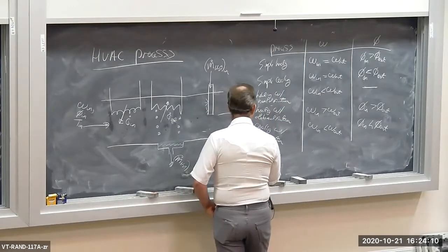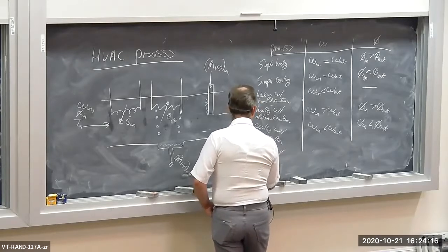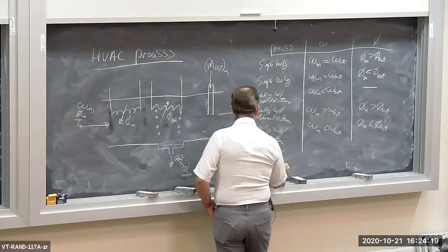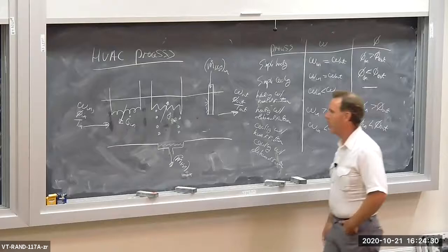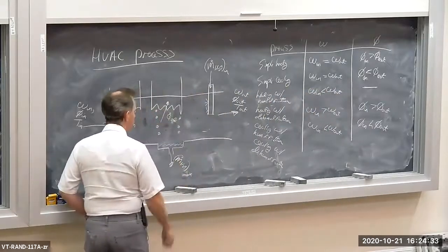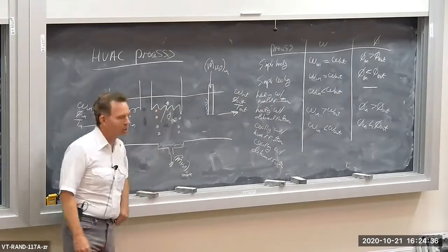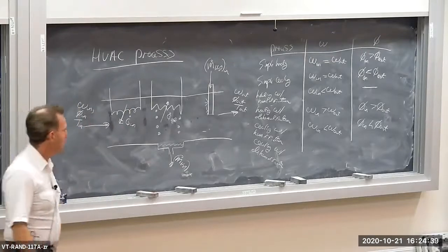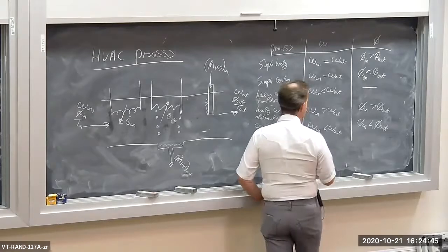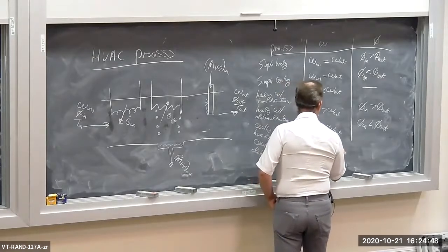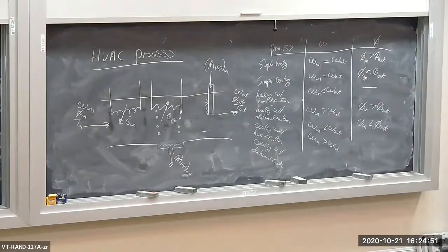And then finally, we have cooling with dehumidification. Dehumidification is where we extract H2O. Cooling is where we reduce the temperature or extract heat, let's say. Well, we could do that with some cooling coils where we siphon off or drain away the condensate that's condensing on the cooling coils. Clearly, the outlet absolute humidity is less than the inlet absolute humidity or humidity ratio.